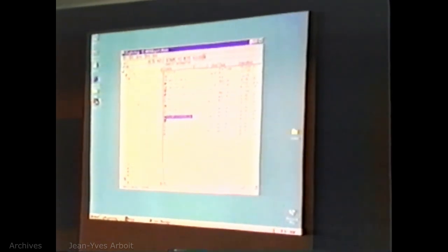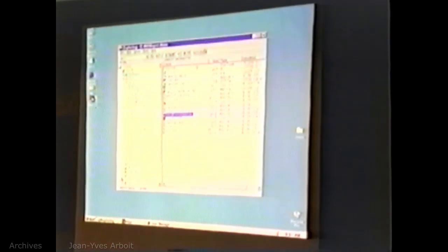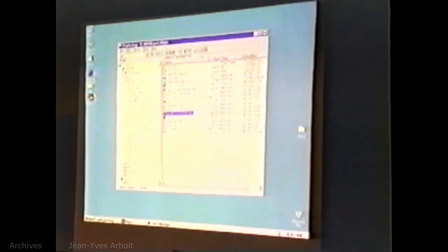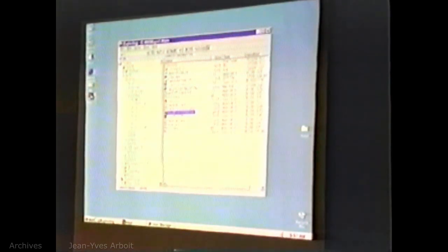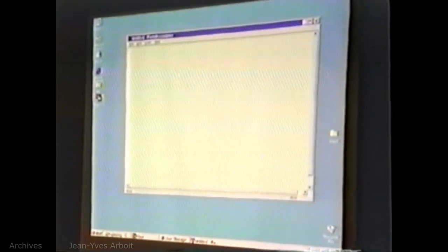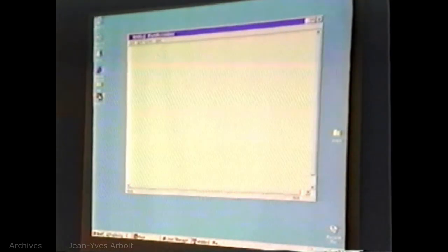You guys know that on F-Check we have a GUI now, so you can open an animation or an image. I'm just going to mention that really quickly because it's a little easier to use. We also have something else called Field Assembler right here. This also brings up the UI for if you need to interlace your fields. Suppose you have a client using After Effects, maybe. So if you're going to import your fields, this is going to be really important. Use Field Assembler, and that also lives in your bin directory.